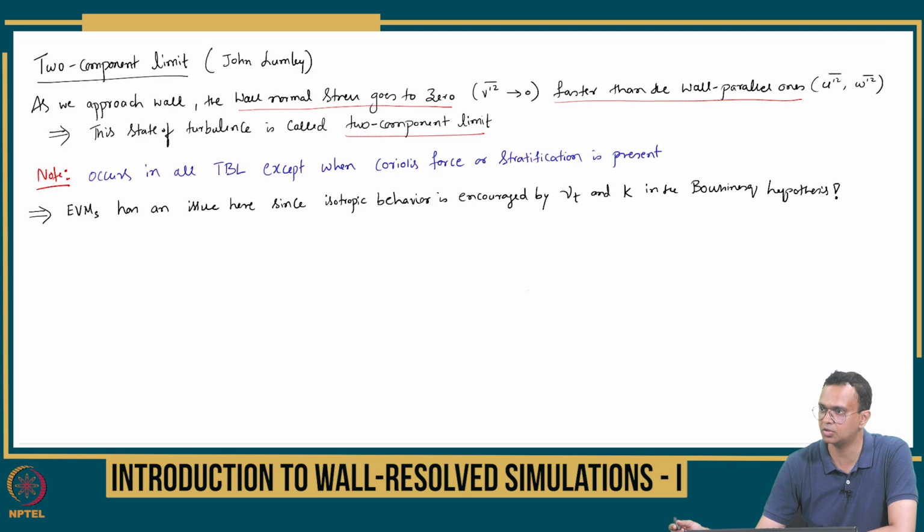You also have eddy viscosity, which is lumping turbulence as a scalar quantity, and we clearly see that VRMS has to damp. So turbulence kinetic energy, when you are computing, is a sum of all the three stresses. Where some isotropic behavior is enforced, it may give higher turbulence than what is necessarily there, because V is now much smaller, it is damping much faster also. So the actual turbulence kinetic energy can be much lower than what your turbulence model, eddy viscosity model, is predicting. Therefore, it requires something to be done.